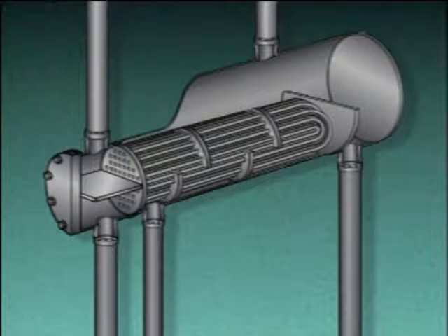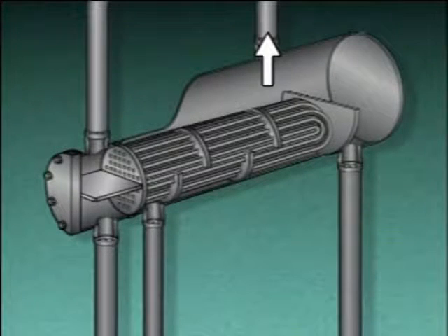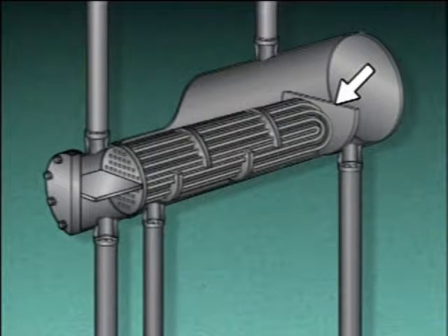They're primarily used to vaporize process liquids from a distillation column and return only the vapor back to the column. Let's look at an illustration of this type of reboiler to see how it works. The major parts of this reboiler include a shell, a tube bundle, a tube inlet, a tube outlet, a shell inlet, baffles, a vapor outlet, an overflow weir, and a liquid outlet.